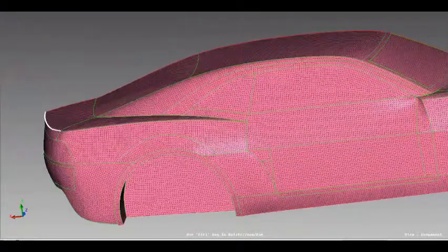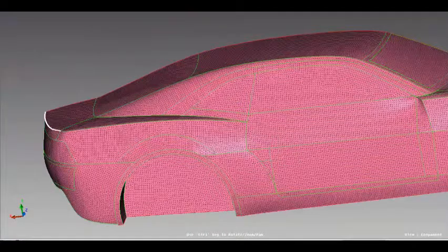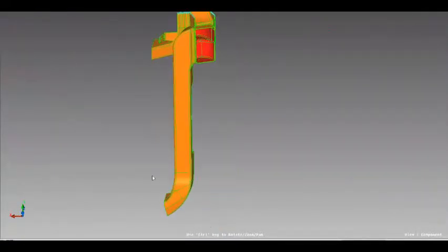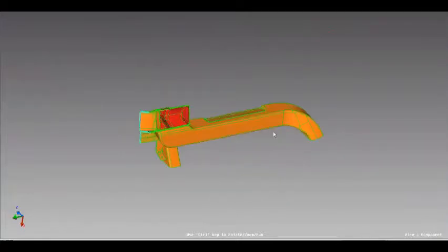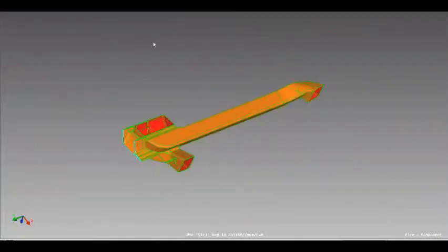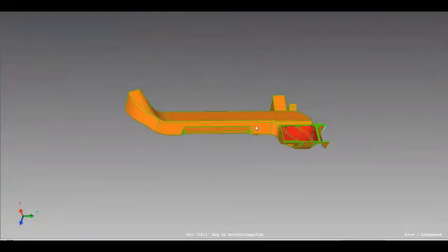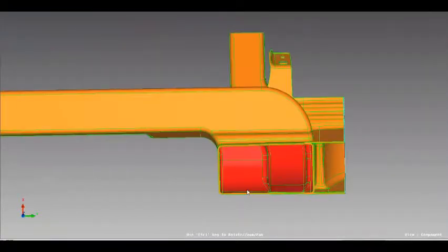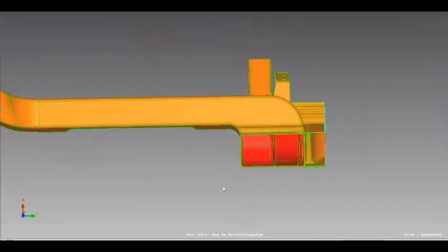With this, now I want to move on to the next demo, which is internal surfaces meshing using the interactive batch mesher. So this is a CAD component, which is a hatchback model, and I want to do the mesh for the internal ducts so that I can study the internal flow. So for that, I have organized the internal surfaces into different PIDs. Now I want to isolate only the internal surface.